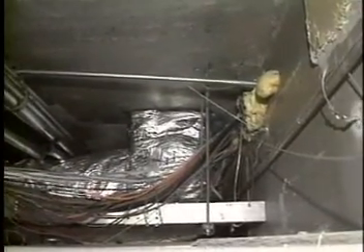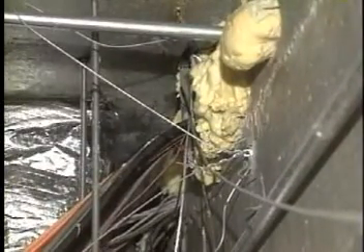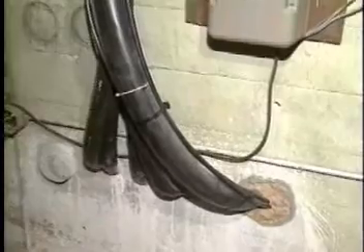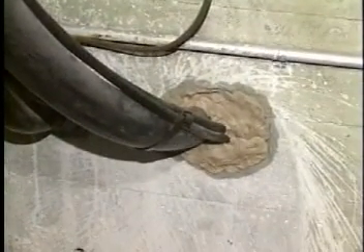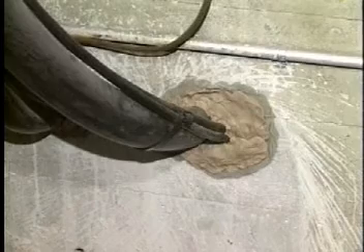Wherever cables, ducts, or conduits pass through barriers, such as floors or walls, fire-stopping material must be used to plug up any openings. This can be done with foams, putties, or other sealants to form an airtight, fire-retardant barrier.